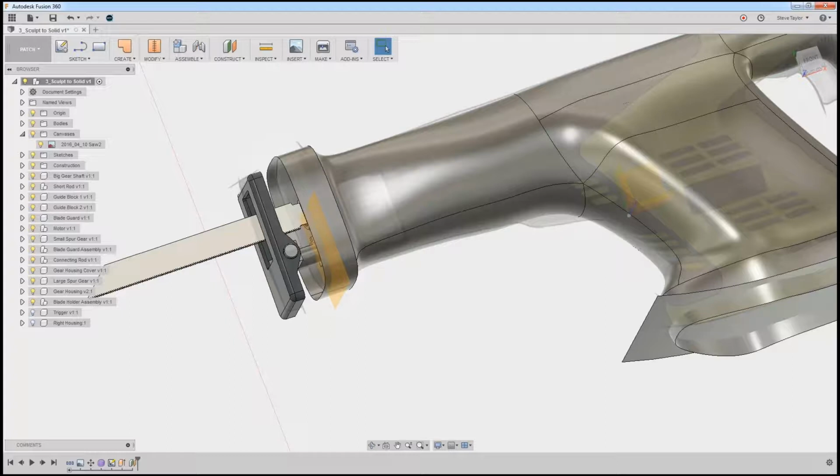For those of you who are Inventor users, you will have heard me mention Sculpt when referring to T-splines and to a workspace. In Inventor, there is a Sculpt tool that allows me to take a series of surfaces, planes or faces, and combine them into a solid model. Fusion 360 has a tool that works essentially the same way and is actually quite clever. This is a very simple model for us to work with. This tool is called Boundary Fill.